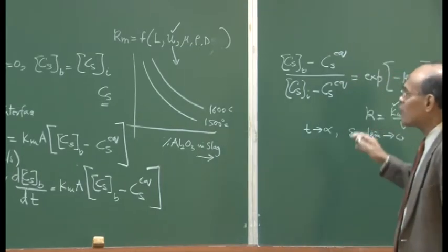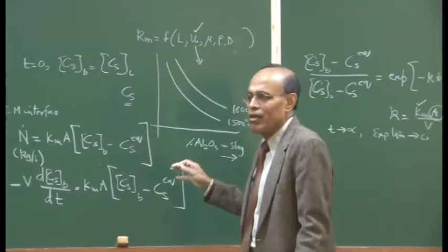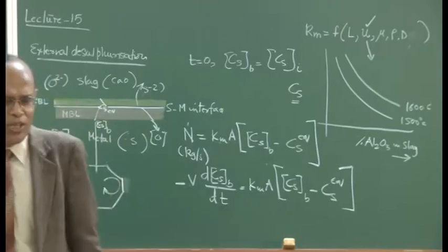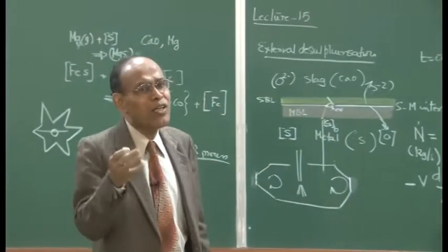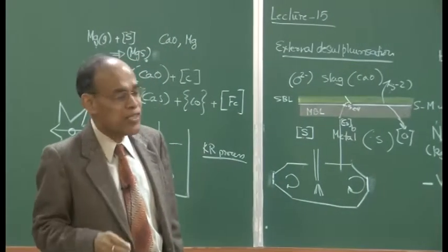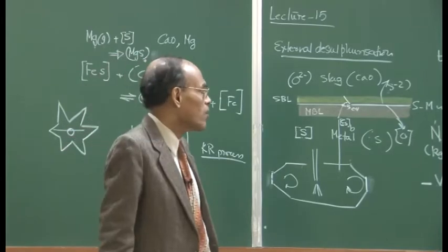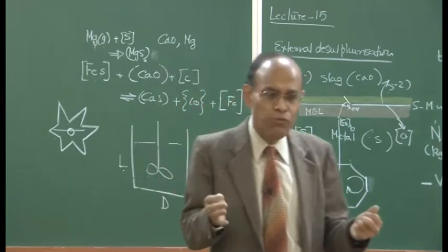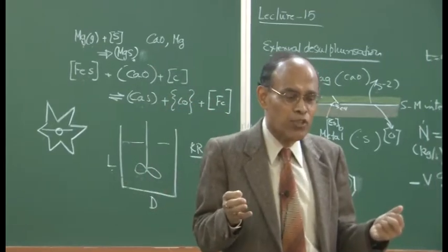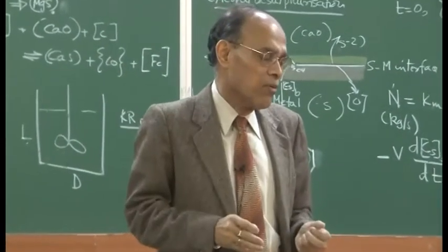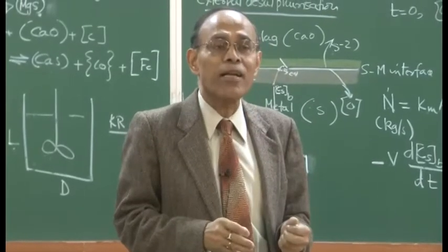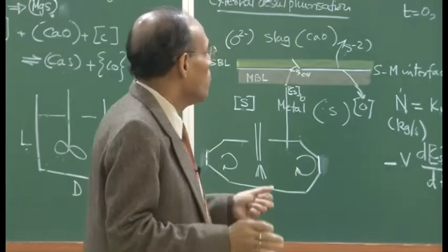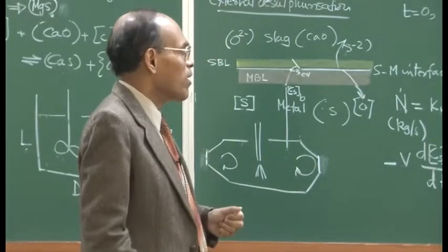Now, I will not discuss dephosphorization as far as pretreatment is concerned, because dephosphorization per se is only used in certain Japanese steel plants that are very highly concerned about it. Sometimes they treat high phosphorus pig iron, and as a result there is an enormous amount of phosphorus dissolved in the metal, and in that case dephosphorization becomes very important.